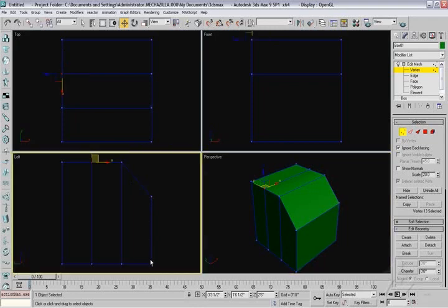and you can go ahead and grab like the lower right hand corner, excuse me. But we want to make sure we grab both of them, so go back and uncheck Ignore Backfacing. So if you uncheck Ignore Backfacing, you can now draw around the lower right hand corner vertices in the left viewport, and then grabbing it by the Y handle here, just put your mouse over the green arrow there, and it should turn to gold, and pull it up about a quarter of the way up your model, considering this is the minimum and again this is the maximum.